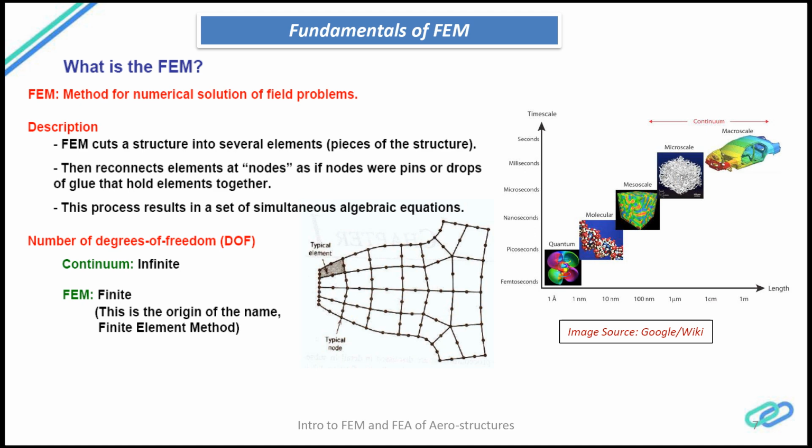This domain is called a structure, the big structure or the global structure, and it is broken down into small elements that are interconnected at some points called nodal points or nodes. Whatever the functions, such as displacement and forces, they will all be computed at the nodal points, and the nodes of the elements should satisfy certain conditions called compatibility conditions. It should be compatible with the nearby or connecting elements.